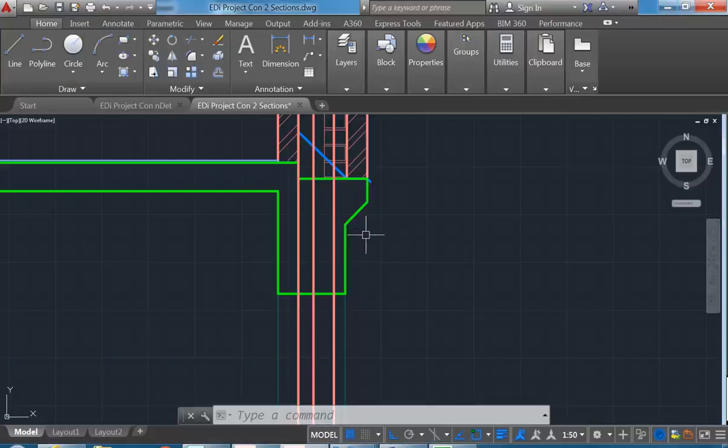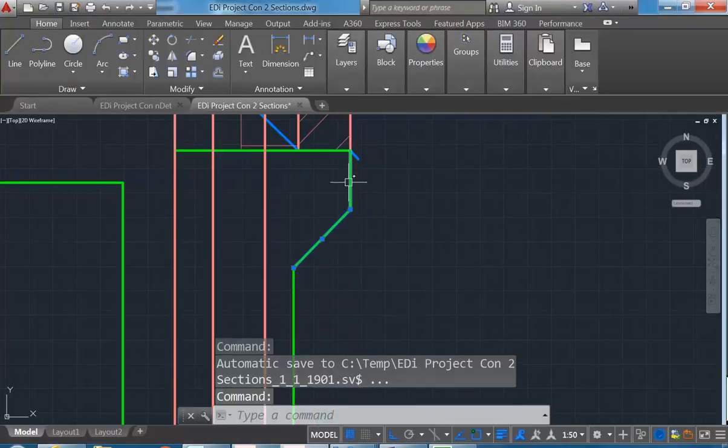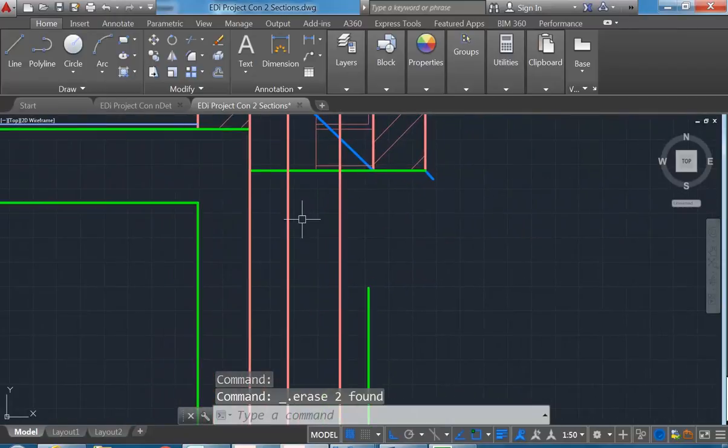And so you can easily count, you can work out it just visually. It's 2 bricks side on, or 1 brick lengthways, so 230. Okay, so that tells you how far from the exterior wall. We've got no slab projection here, so that can go.